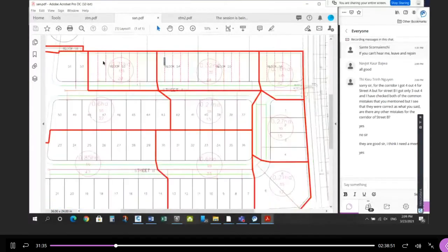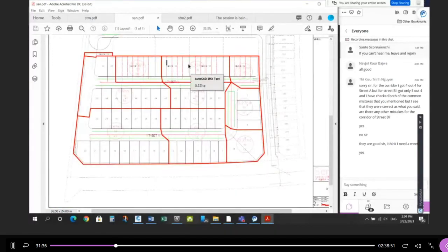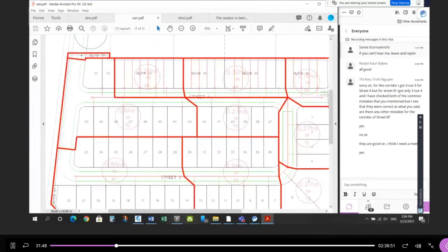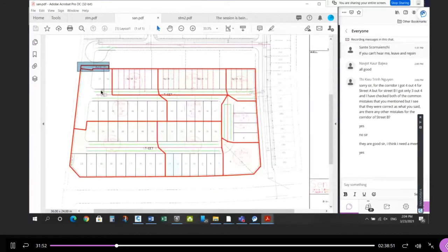The other thing I'm looking for is the drainage bubble. Make sure you put in an area. See, technically here, somebody forgot to label this little piece that's going to go the other way, which is critical for the analysis, right? Is that too big to go the other way? We proved it's not. So you should label each one. So I might have taken a mark off for missing bubble data here. These pipes, this one and this one, had to be divided into 2 parts, townhouses versus singles. So that had to be present. So that was most of the design consideration.